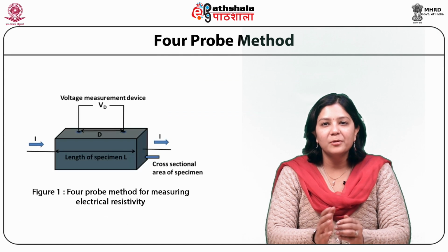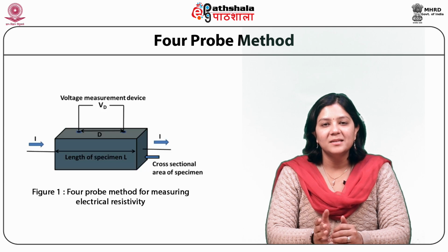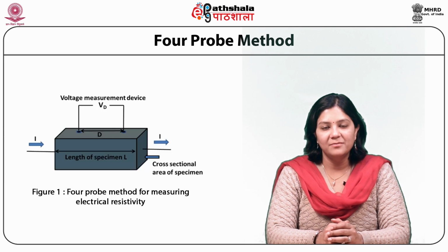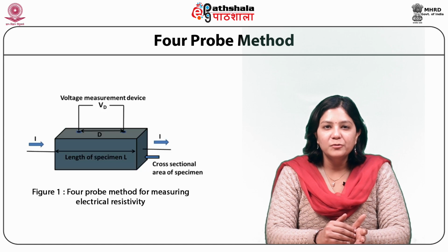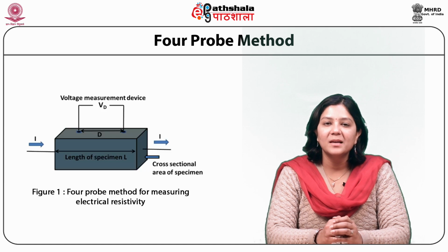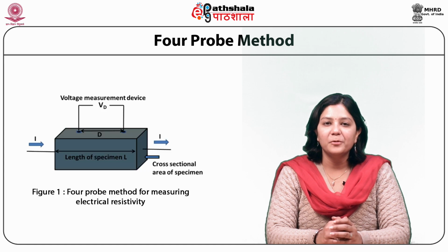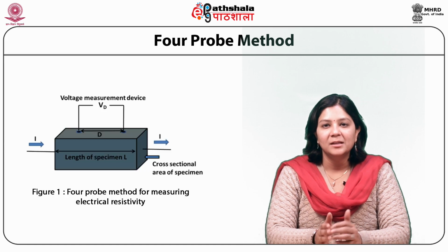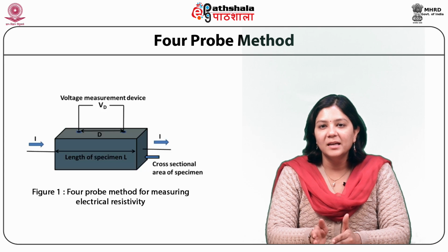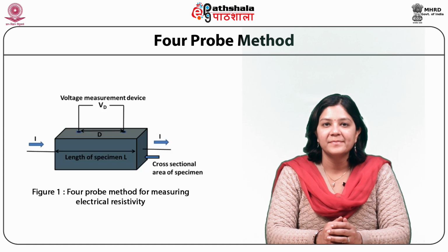The potential probe is the most commonly employed method for measuring the resistivity of samples with low resistance value. Potential drop across two probes is measured and the gap between them, d, is taken as the sample length L. If the probes are not point contacts, the true value of probe distance is the gap between the centers and not the shortest distance between them.